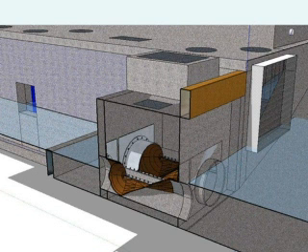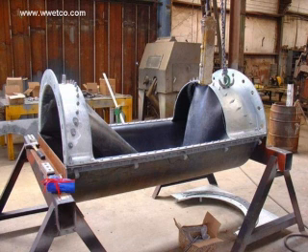The dry weather function, because we had a dry weather bacteria problem, is to disinfect the dry weather flow. That dry weather flow actually goes through UV disinfection. And then when it rains, the flow control makes the level upstream rise up, and it goes into the filter system and then back through the UV system before it's discharged. This is a graphic representation. You can see better the flow structure across the creek.